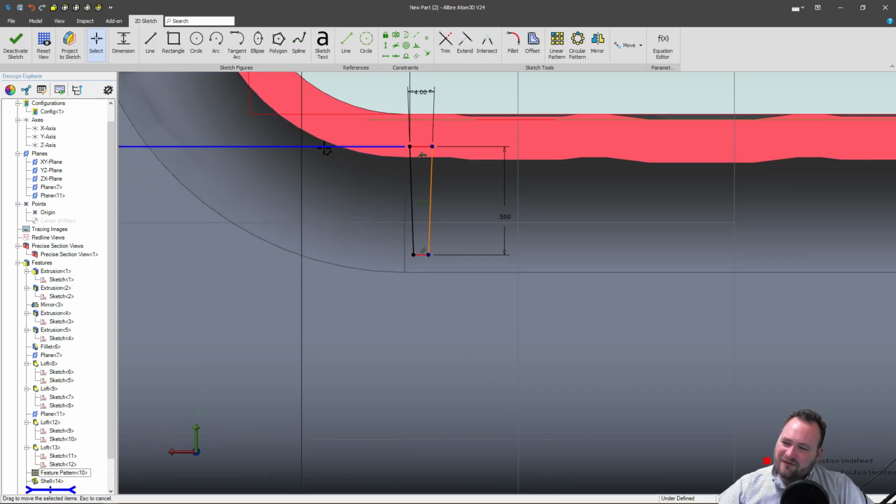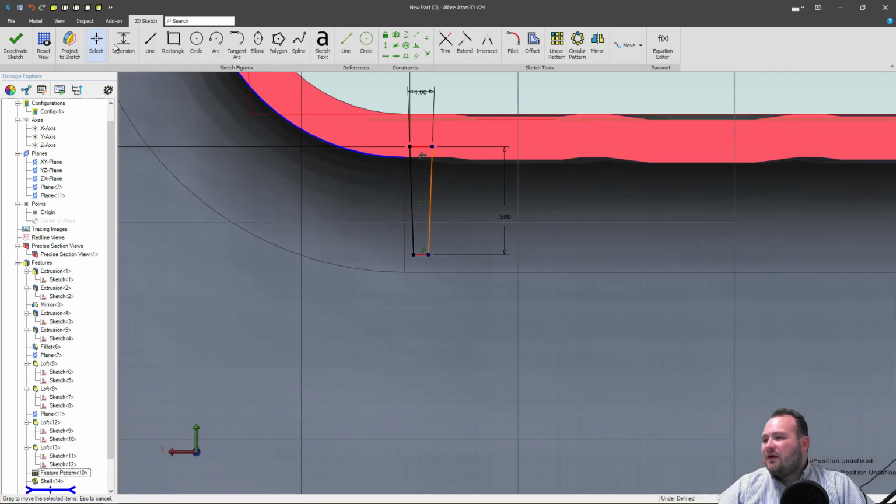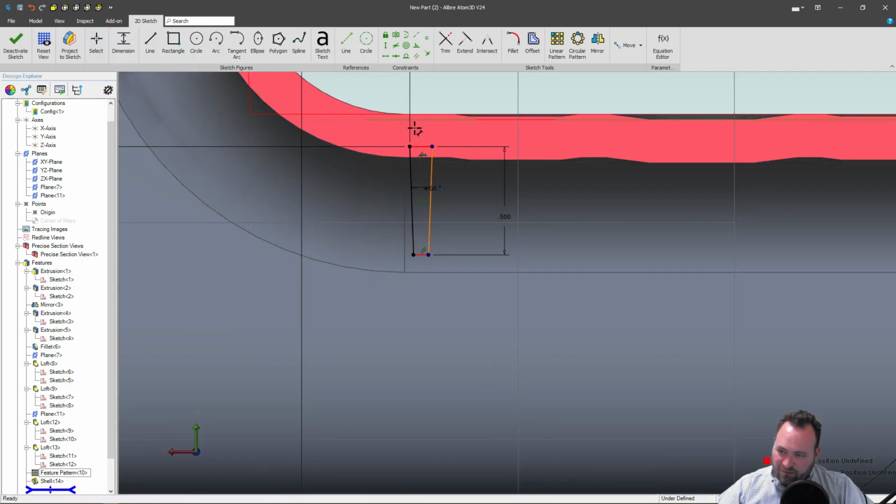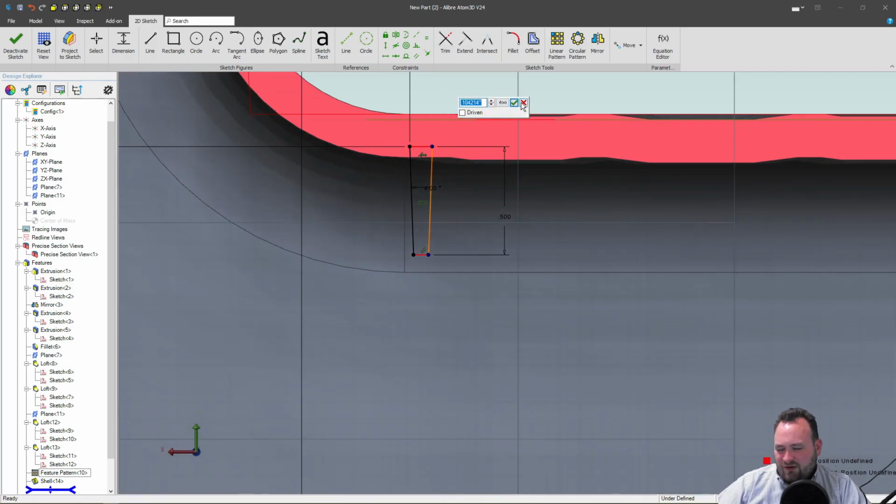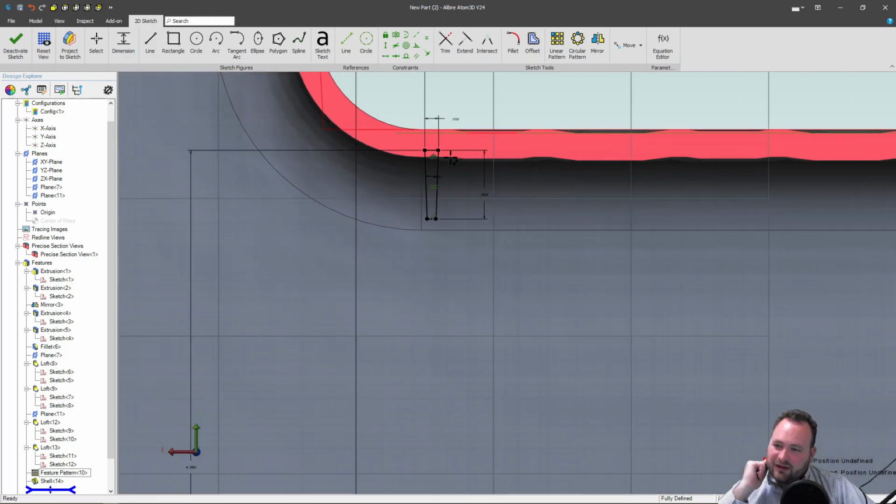Now, rib width you define from the base, and you would have fillets down here. I'm kind of omitting those for now. But your rib width is really dependent on your material. Yeah, there's my rib angle. So if you're working with an amorphous material, amorphous is going to be your wall thickness, all right, 0.2, and the maximum allowable width for the general rules of thumb is going to be times 0.5, right? So amorphous materials is your wall thickness halved is the maximum thickness of your rib. If you're working with a semi-crystalline material, you can go your wall thickness times 0.75 or 75% of your wall thickness. So we've got this rib profile hammered out.